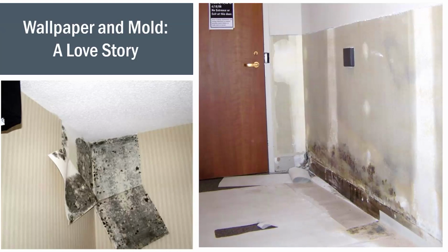I had a hotel in Alabama with a mold problem, and it was legacy. They had put up wallpaper many years ago. It was a nice neutral color, so they hadn't felt the need to redecorate. So you do see this sometimes. So if you walk into a room and it's painted, you also want to look and make sure that it's not painted wallpaper, because that's what they had done in this hotel. It was like when they started to knock down drywall to expand some of the rooms.